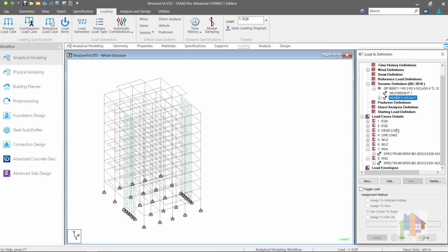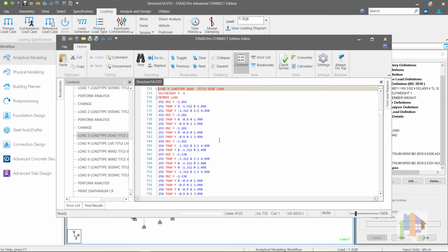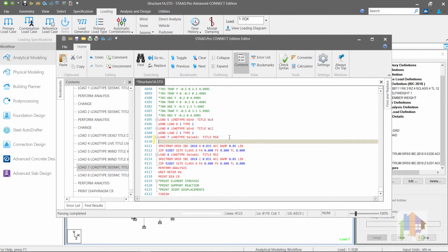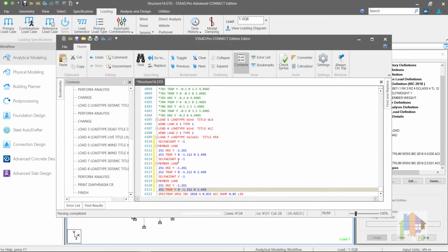So under the response spectrum load case, you need to define all the seismic weights again in three directions. This time, you can take help of the input editor. Open the input editor. Copy the dead load items from primary dead load case, say the first three load items, and paste the load values 3 times under the first dynamic load case and modify the load direction from Y to X and Z for the rest of the 2 items so that the mass model is formed in X, Y and Z directions. There you go. The mass model is now ready.